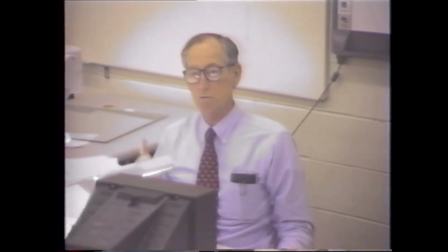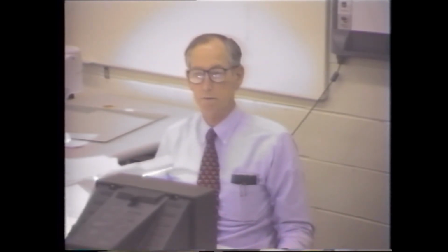Again, we have the question of whether you'd be given data in standard cubic feet per minute or in actual cubic feet per minute. If it's actual cubic feet per minute, you need to know the corresponding temperature. If they give you a question in standard cubic feet, it says the flow rate is so many standard cubic feet per minute, that always refers to the standard temperature, 77 degrees F, 25 degrees C.